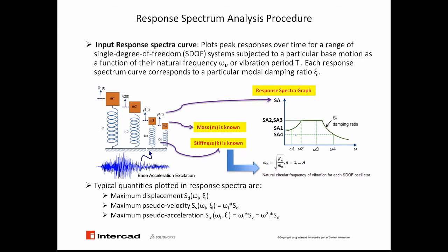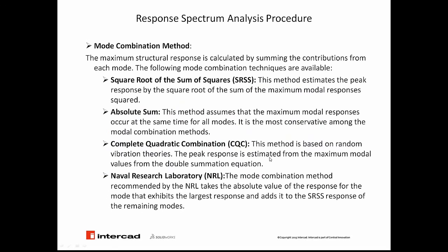If we have these single points and we would like to add them together and see the responses of the structure, we need to go to the second step: combining the modes of vibration. The maximum structural response is calculated by summing the contribution from each mode. We have different combination methods available in SolidWorks.